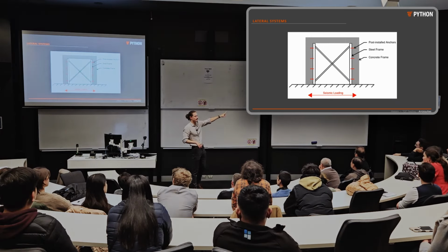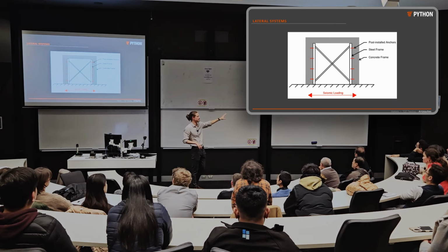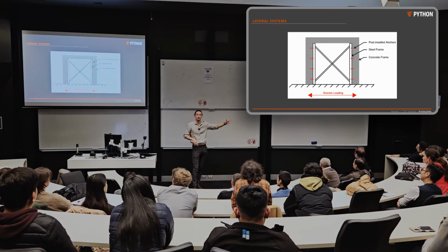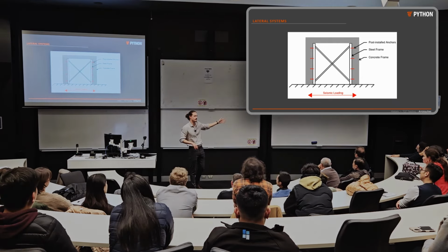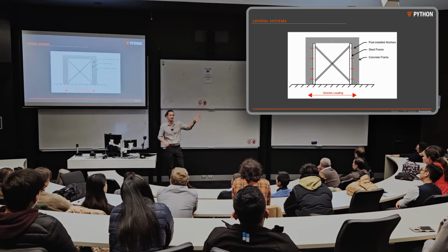Do we expect in that scenario cracking representative of reinforcing yield in the columns? All right, we've stiffened the system. The columns arguably aren't going to be taken to yield of their reinforcing. The cracks are probably going to be much smaller than 0.8 mils. C2 capacity is conservative. Probably by quite a lot. Again, not necessarily a bad thing, but it's something to keep in mind.